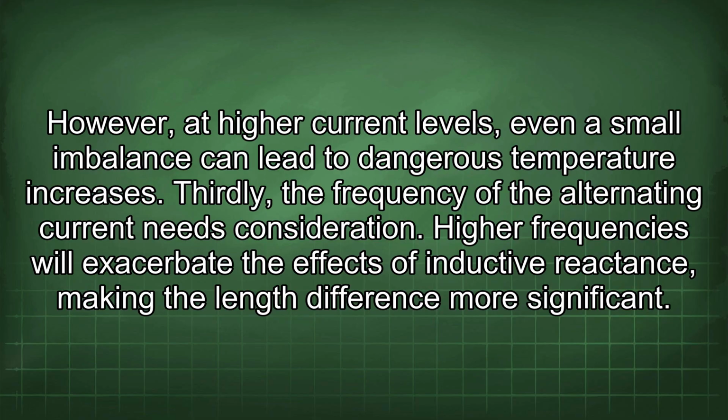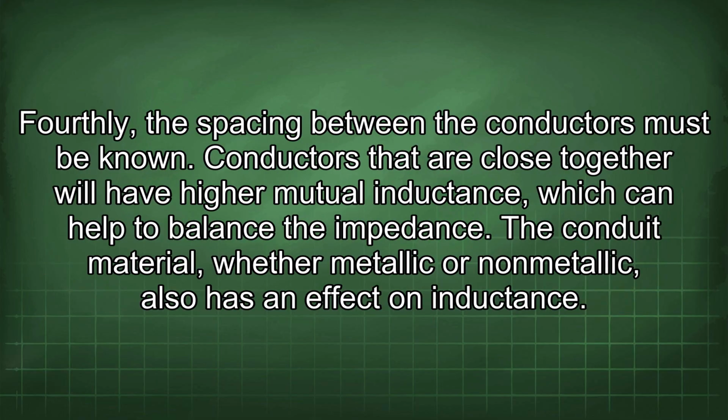Thirdly, the frequency of the alternating current needs consideration. Higher frequencies will exacerbate the effects of inductive reactance, making the length difference more significant. Fourthly, the spacing between the conductors must be known. Conductors that are close together will have higher mutual inductance, which can help to balance the impedance.